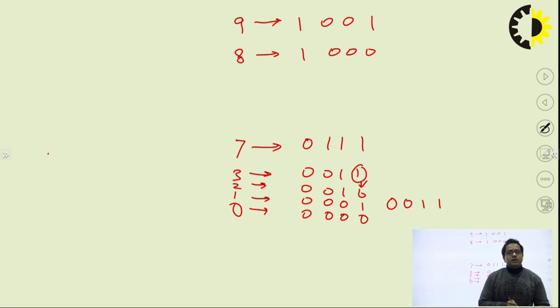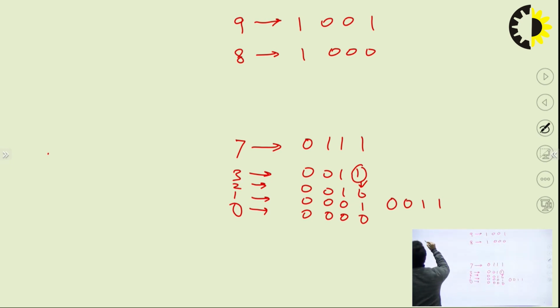That means there is some circuitry problem with the latch. There is no proper synchronization, because of which all 4 latches don't respond at the same time. That is the problem which arises because of improper synchronization. So we need another kind of sequential circuit which has proper synchronization for changing the sequence. That is the need, that is why we have flip-flops. Flip-flops are used basically for proper synchronization.